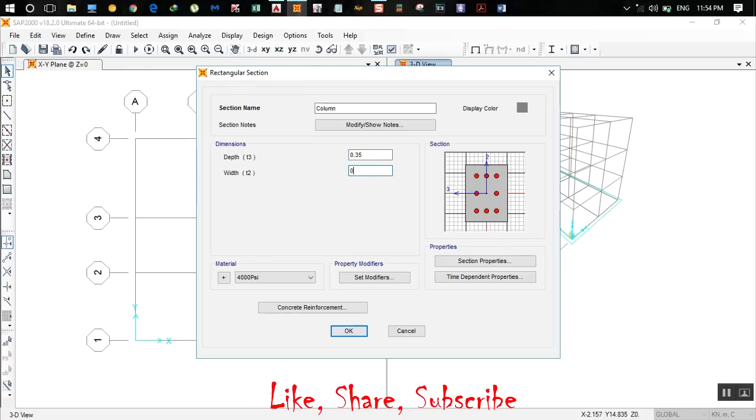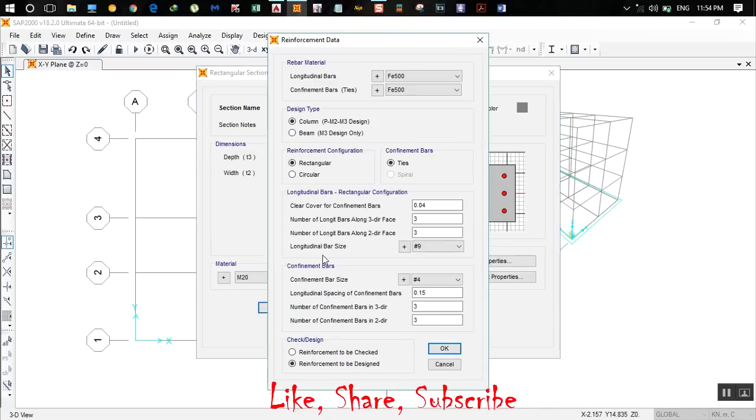Okay, so width 0.35, and the material I'll be taking M20, and concrete reinforcement. So longitudinal bars FE500, this is fine, and confinement bars also FE500. So design type is column. So reinforcement configuration is rectangular, and clear cover for confinement bars is 40 mm, which is fine.